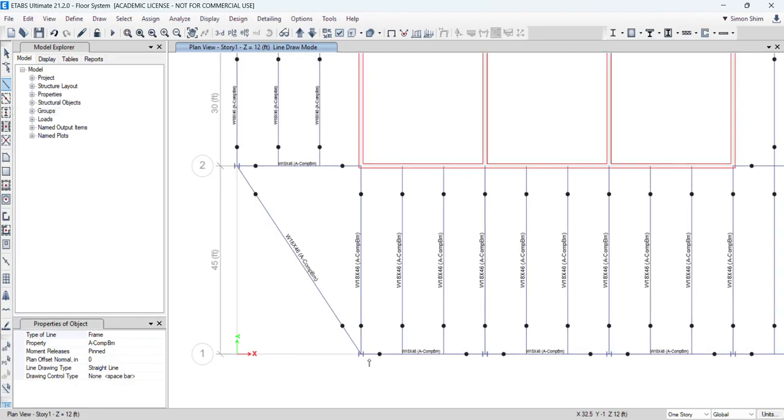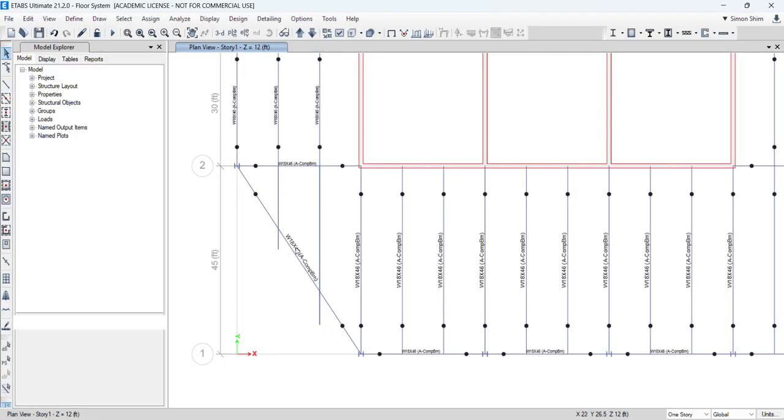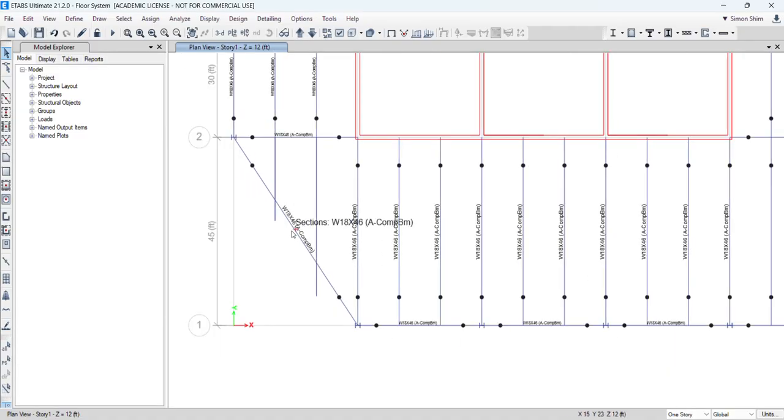So here, assume that you have this kind of chamfer corner. How are you gonna draw this, right? Because in order to do this, you need a point here. But the thing is, ETABS has some great snap tools. So when you click and move this, the color changes to yellow, green. So right click, then basically you draw the beam more parallel. Typically it's hard to find this intersection point exactly.